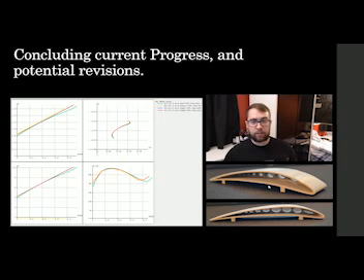The lost lift could be negated with winglets to compact vortices. The instability issue was resolved at 10 degree dihedral, although this requires further testing once the wing is mounted high on a fuselage.